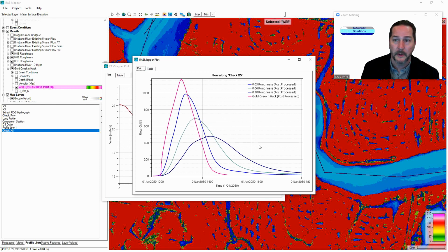If you had real world measurements out here, or you had a rainfall runoff model and you're trying to match that, in some cases you're slowing down the flow and getting less flow in the system, but then that flow is higher because of the higher roughness. So that's where this depth varying roughness can come in handy. But be careful what's really going on.